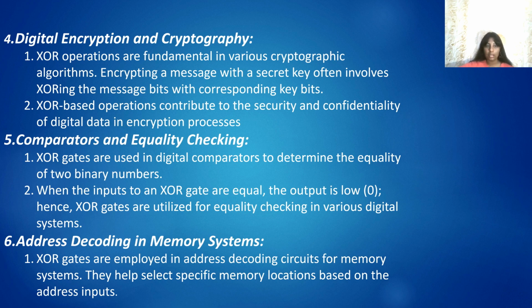Fifth one, comparators and equality checking. XOR gates are used in digital comparators to determine the equality of two binary numbers. When the inputs to an XOR gate are equal, the output is low, which is 0. Hence, XOR gates are utilized for equality checking in various digital systems.